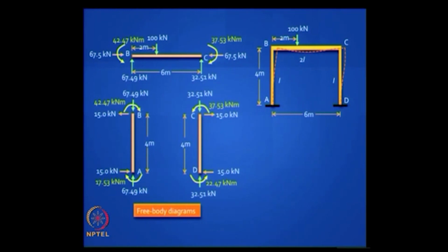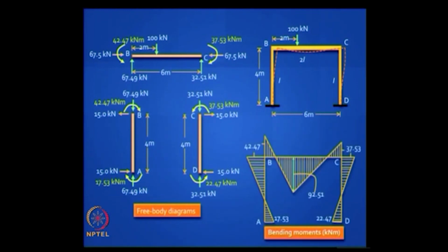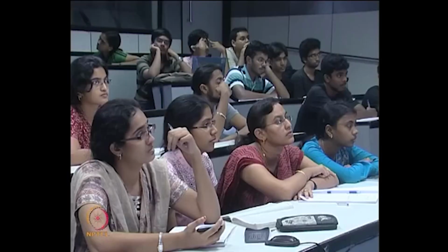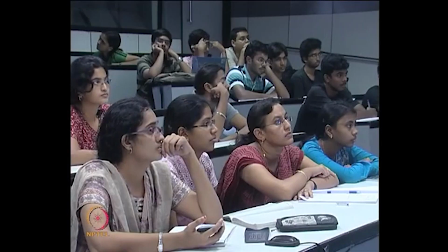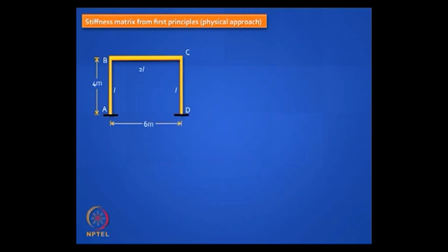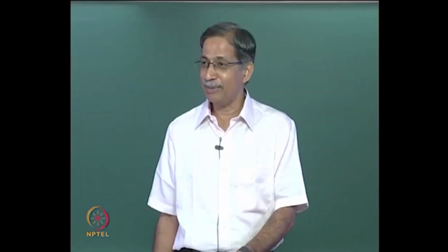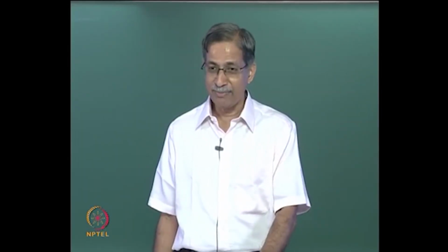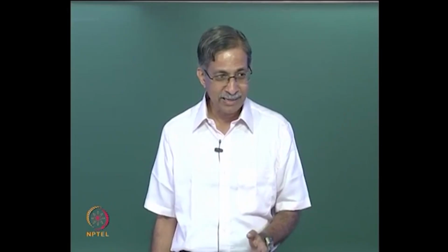Powerful method, agreed? Then you can draw the bending moment diagram, it will look like that. So you are not afraid of sway, you know how to deal with sway, okay. But if you have multiple sway degrees of freedom, you have to do it a little more carefully. Now I want us to go through this small exercise of generating the stiffness matrix of this frame from first principle. Shall we give it a try?